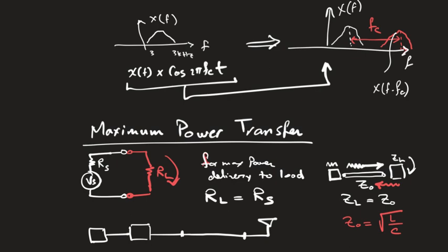And in order for this whole system to be efficient, the main idea is that at any point, the impedance you look at here, Z out, should be the same as the impedance that you see from this side, Z in, when you cascade components, right? So if I go to this point as well, whatever I see from here, Z out 2, should be the same as what I see from this side, Z in 2, and so on, right?